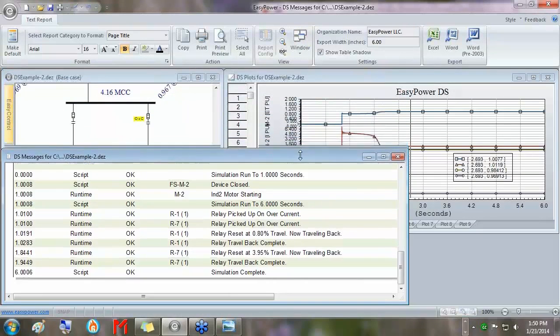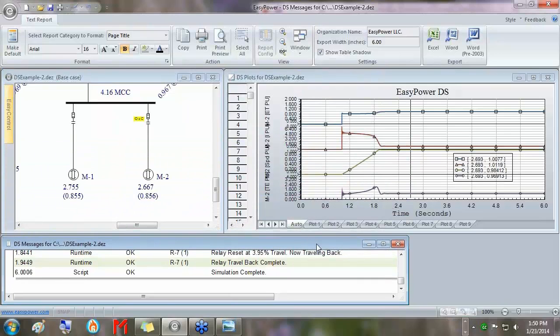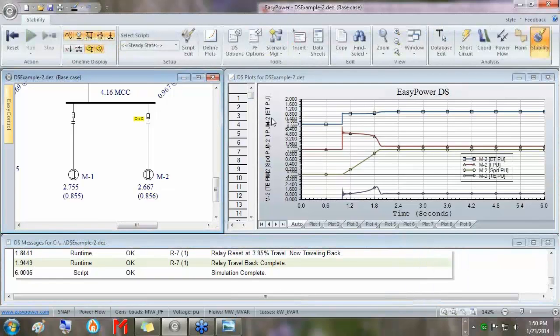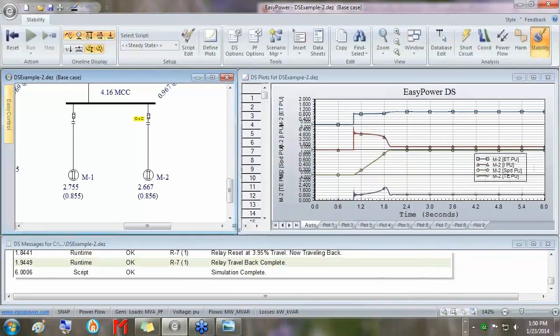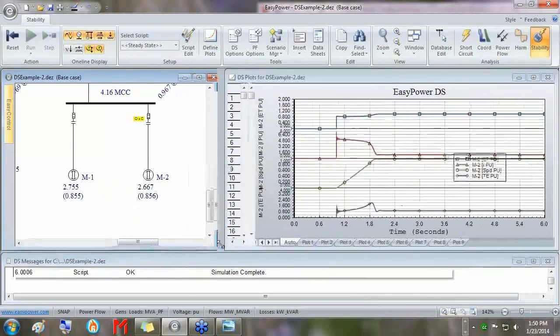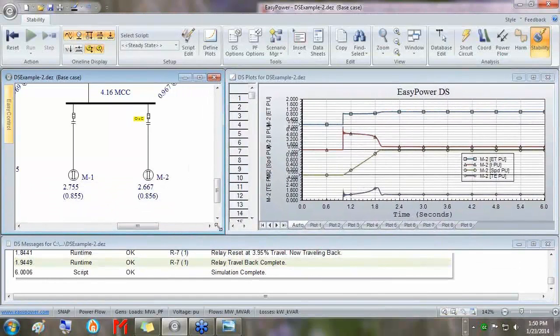So valuable information here. Notice a nice trick. If you're in here, you have these 3 windows showing, you hit F8 and it puts them all back in order. Another trick, the bottom right-hand corner here of the main one-line window, drag it and they follow. So you can quickly resize your windows.